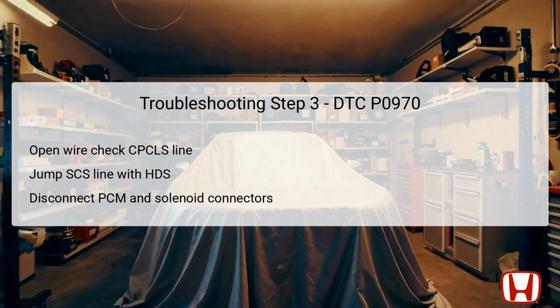If continuity is established, it indicates that the wire is intact and functioning correctly, potentially leading to an update or replacement of the PCM if the software is outdated. However, if there is no continuity detected, it signifies an open circuit needing repair.